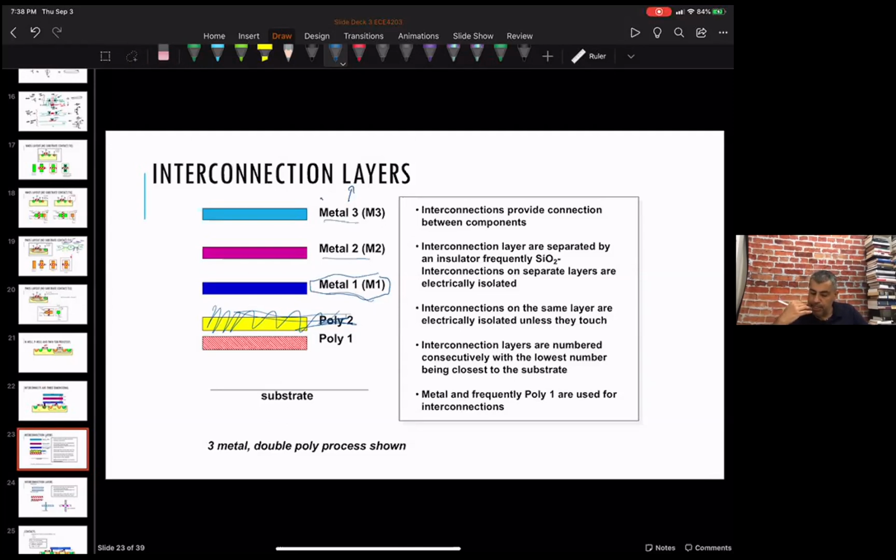And then if there are metal layers on the same layer, so let's say if you had two metal 2 rectangles. So let's call this metal 2. You drew this in metal 2, and then you drew this in metal 2. Those two rectangles will electrically short together because they're on the same layer. When the foundry makes them, it'll make it like a cross.